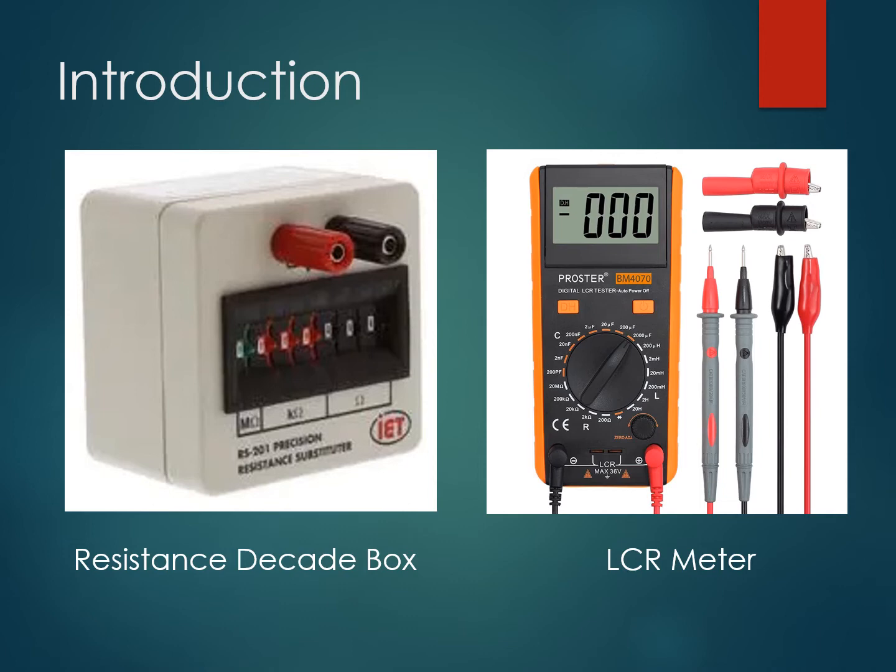The experiment begins with calibrating the given values of resistance, capacitance, and inductance with an LCR meter. For quick changes, decade boxes were used to set up each of the values. So the purpose of the experiment was to monitor the voltage responses over the capacitance for RC and RLC circuits. Through experimentally determining the results of the voltage gaps, we can calculate other helpful information such as the time constant, damping ratio, and natural frequency. And this information is helpful because it's not just limited to RC and RLC circuits. It can be applied to almost any dynamic system.